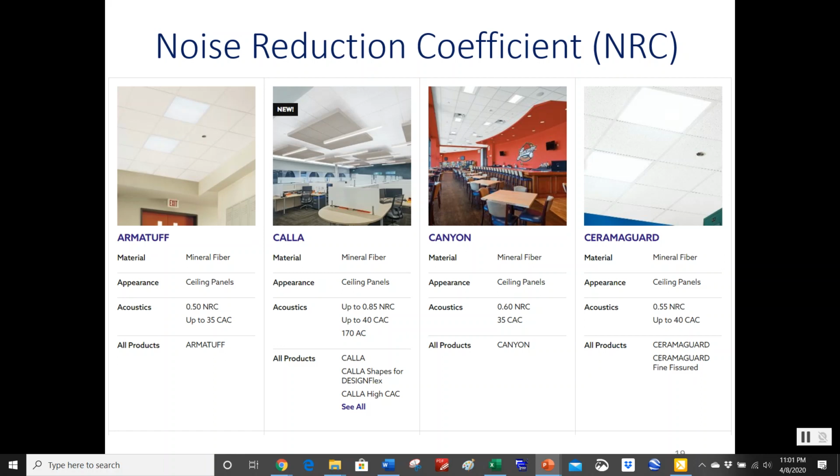And if you did that, you wouldn't want that high absorption level of the fiberglass. You wouldn't want that because it would absorb the sound generated by the people down in the room, but it's going to let that fan coil unit sound just pass right through it. It might be the same thing if it's the top story and you have the packaged unit on top with a lightweight roof, or say you even have a concrete roof, but the ductwork penetrates down, so the sound just breaks out of that thin sheet metal of the ductwork.